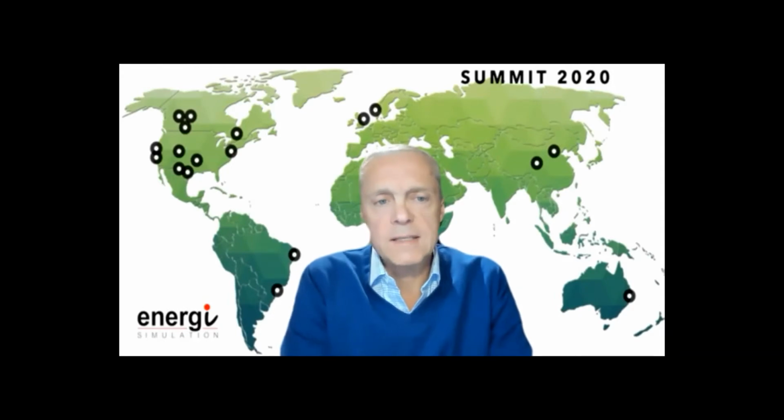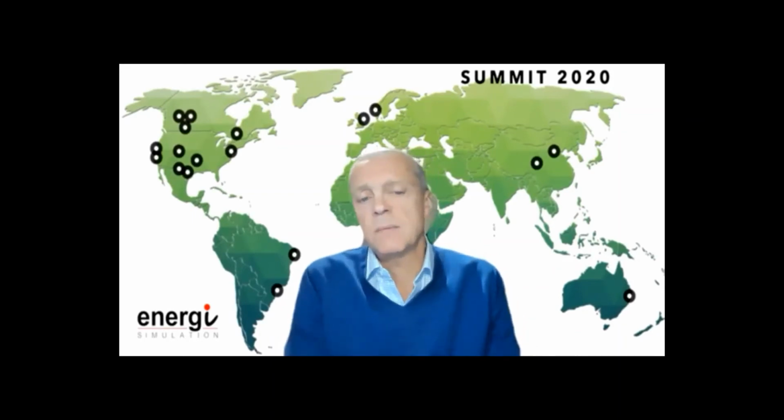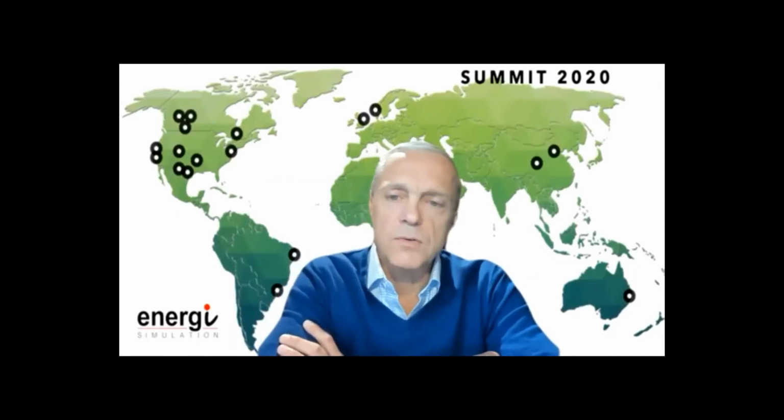More on the oil and gas side of the world, there are borehole breakouts and hydraulic fracturing. In the geotechnical world, foundation engineering design and things like that have used pressure meters, which I'll talk about in a bit. But there are other ones: acoustic methods, earthquake focal mechanisms, geophysics, seismic. You see some of the compliance tensors, Anderson's definitions of stress regimes.